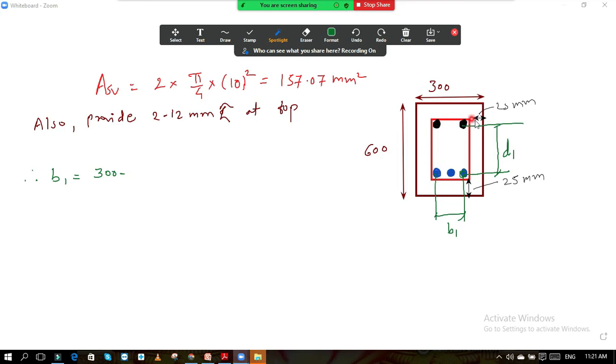Okay, to hang, to provide the anchorage to the stirrups. First thing. Second thing is, these two bars are provided for the ductility purpose, to enhance the ductility of the structure, to enhance its performance against the earthquake. Okay, and it is given by the IS code of earthquake by designing the earthquake resisting proof structure.